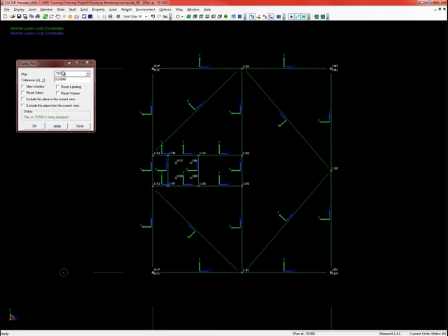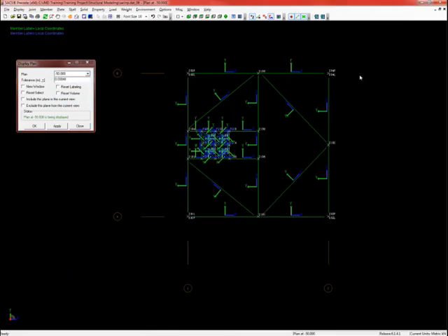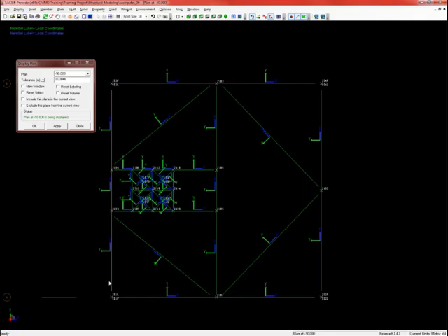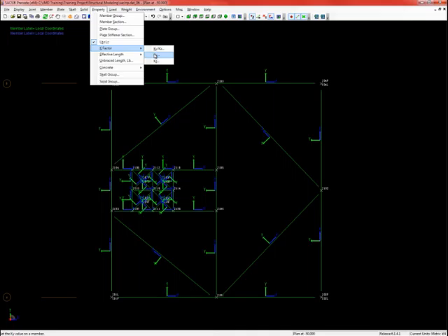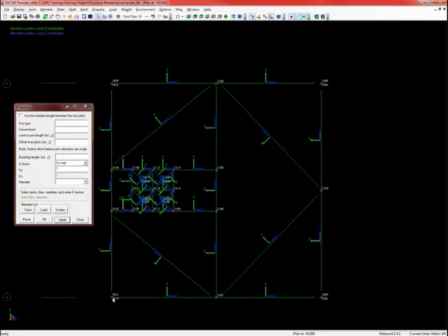We're going to go to the next elevation, so display plan, we'll go to the -50 and apply. And we're going to do the same thing. It's going to be rotated about the Y. So we'll go to property, K factor, KY. Our first joint and our second joint, the end joints. And then we'll hold down, click all the members. Right click apply.